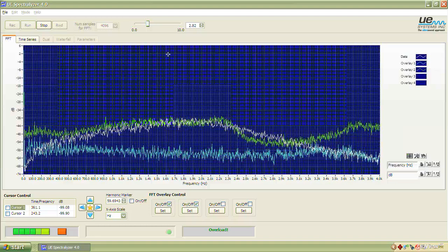These up here would be real-time and record mode parameters for the channel, sample rate and resolution, being set by your computer at this point, because you have UltraProbe plugged into the computer and you're recording that way. And so you can decide where it records and what resolution you want it at, okay? And then the chart background. Okay, we've changed this, we've played with this. This is really easy. Reset the default, just very easy to get it back to what it was.